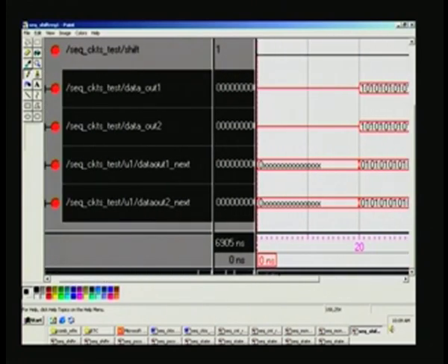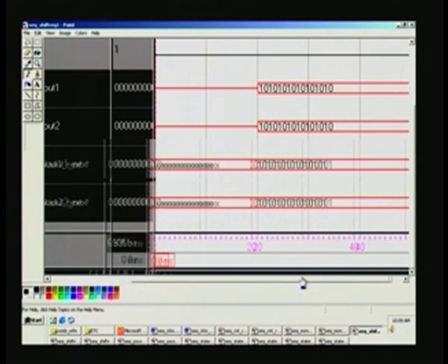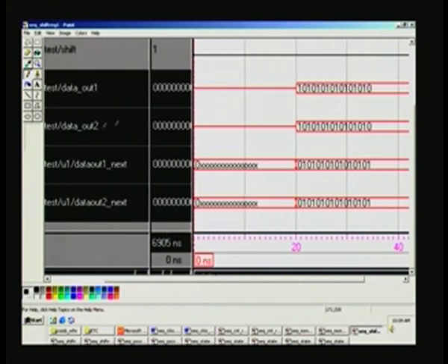So, data out is here. It is enough if you have a look at the data out. Actually we will just have one data out next. If you see, it will always pre shift. Because it is a right shift by 1 bit, 10 has become 0101 here, because it was right shifted. So this will be assigned to this only with the following clock edge.